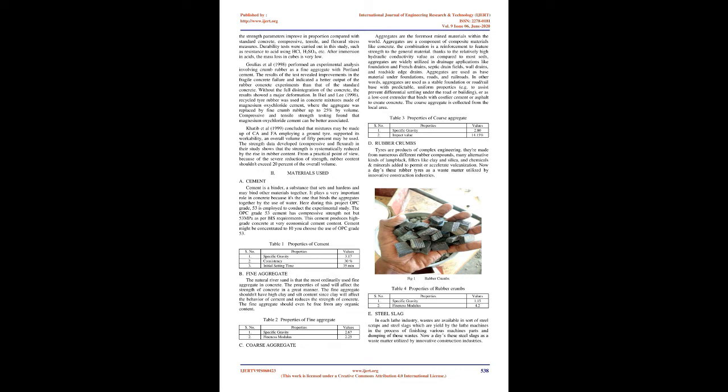conducted their experimental study by substituting steel slag for fine aggregates and/or coarse aggregates. The authors concluded that both fine and coarse aggregates in separate combinations can be replaced by steel slag but cannot be substituted for fine or coarse aggregates in a single mix. They indicated that steel slag could be used more advantageously as a coarse aggregate rather than as a supplement for fine aggregate. The increase in the substitution percentage increased the concrete weight. Compared to traditional concrete, an improvement in the flexural strength of concrete was found.